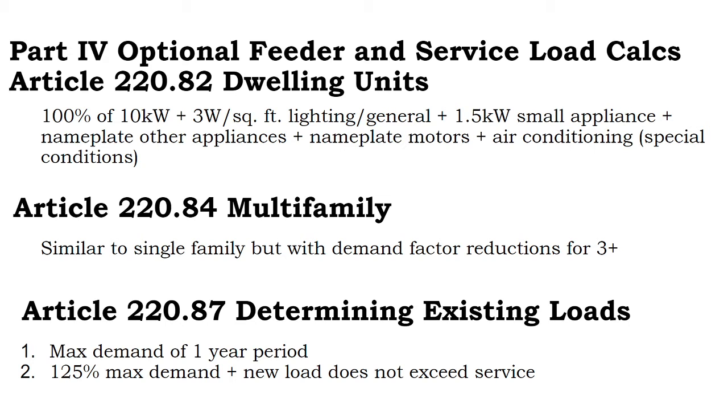A common one is people looking at commercial systems, and you have to start out with, okay, am I doing a 480 volt commercial system or a 208 volt commercial system? That will impact your product selection for inverters, for example.